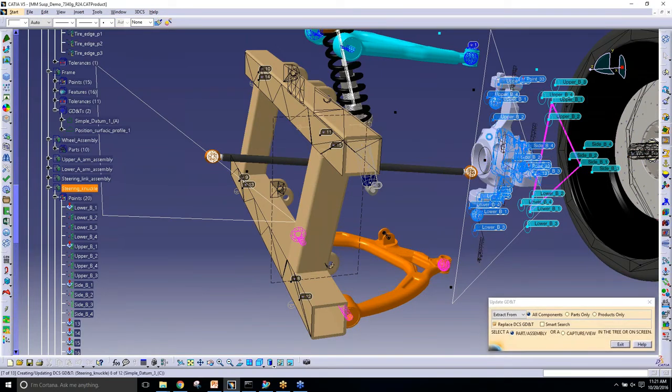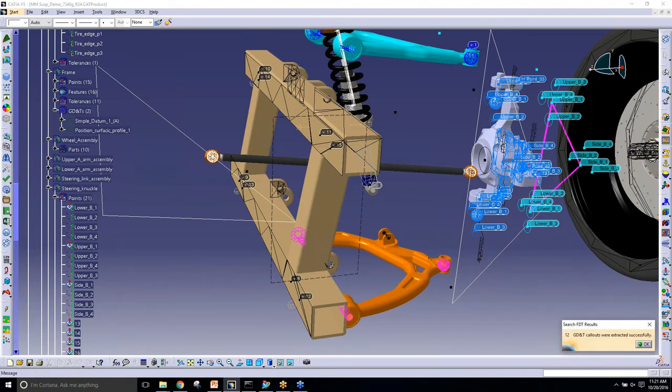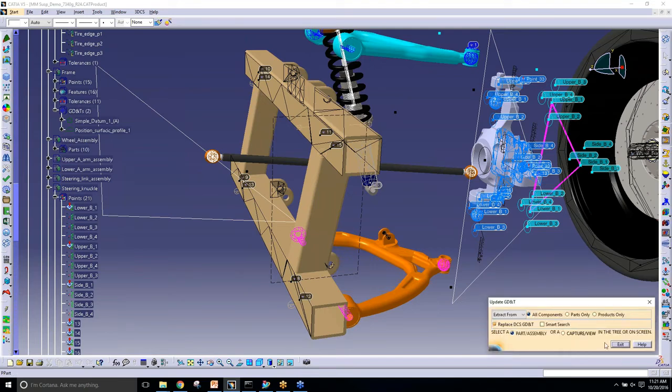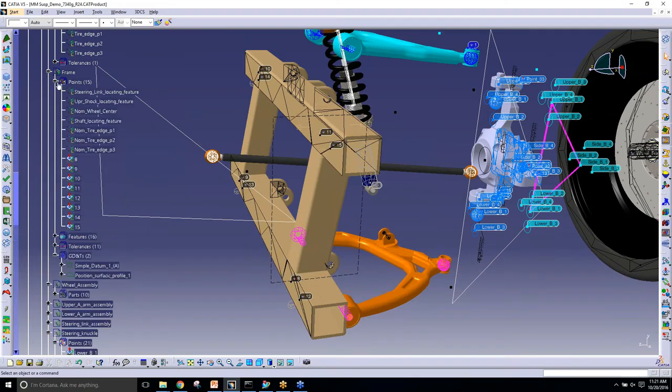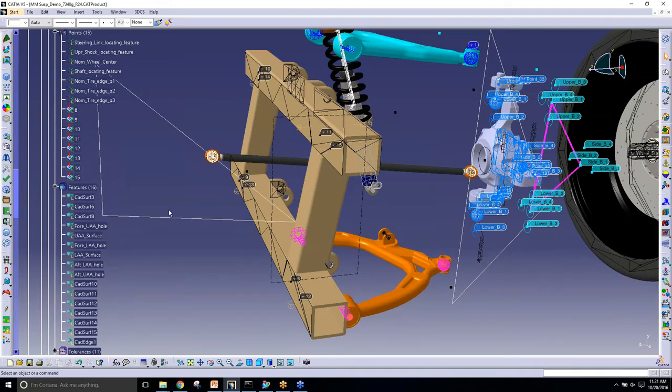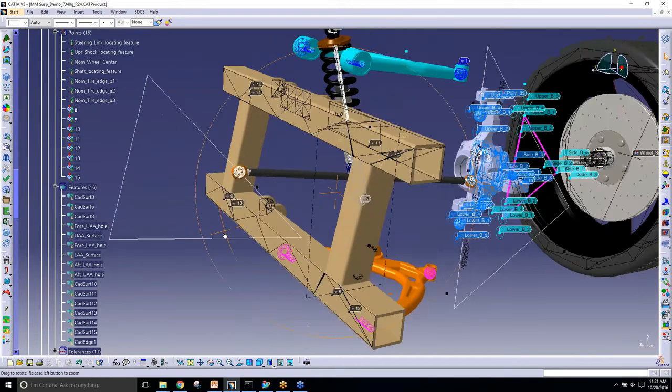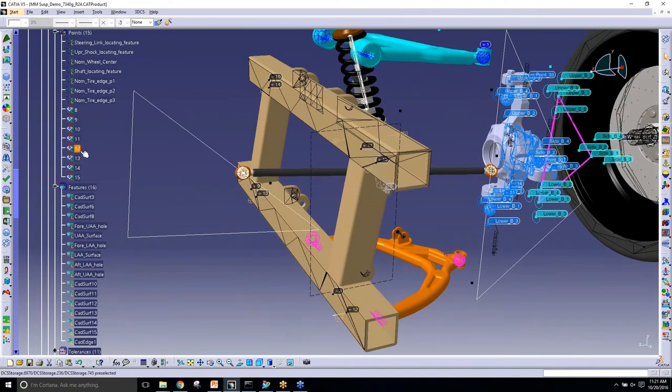So it's just pulling over, if there are datum features, it's pulling that. It's got the tolerances. It's got the CAD points, all being drawn in straight from the CATIA and automatically being applied to your model. Right. So if your model's already been toleranced and had GD&T added to it, there's no need to add 3DCS tolerances unless you've got additional tolerances you want to add onto it, or if you're doing something like the fixtures or additional process. Right.